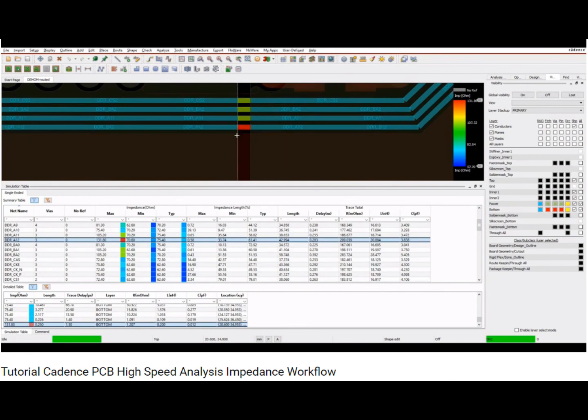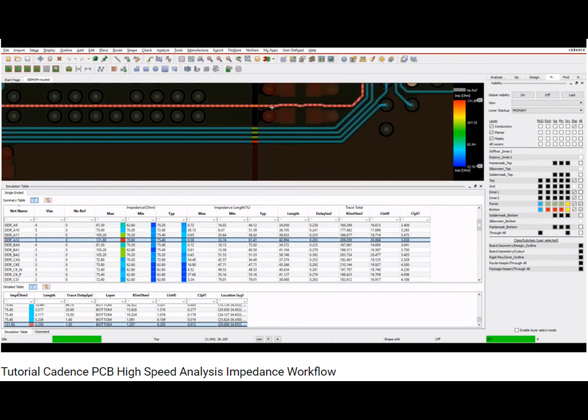So yeah, it's quite a short length of track. It might not cause you any issues, but it's something that you might want to consider. Maybe adjusting the plane or splitting the plane, moving it somewhere else, so that the tracks are 100% covered. But that's for you to decide.